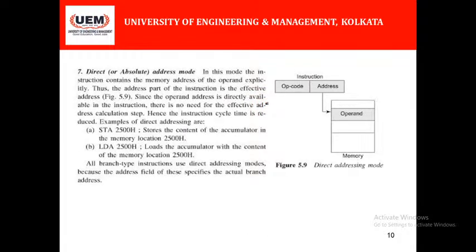Next, direct memory addressing mode or direct addressing mode. For example, STA, or say LDA 2500H. It is a hexadecimal address. LDA is specified in the opcode field of the instruction format, and 2500 is specified in the address field, or operand field, of the instruction format.